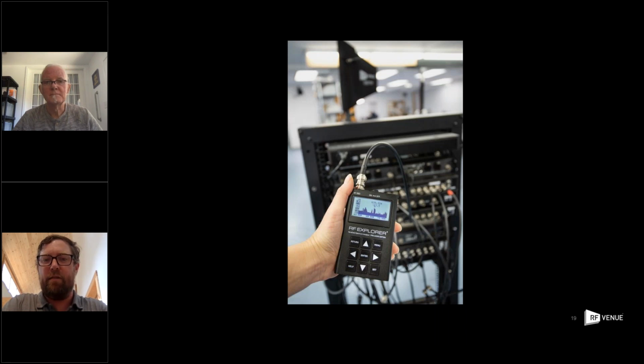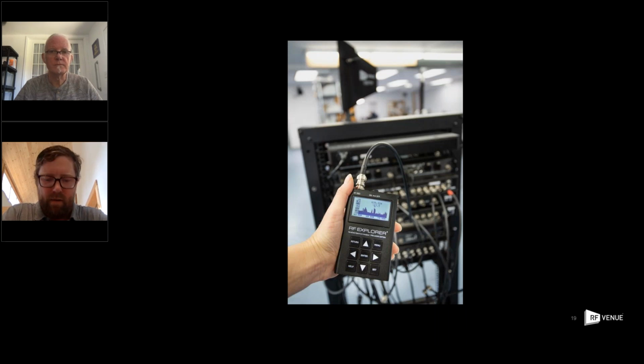If you've got a bunch of wireless mic signals that are, I don't know, minus 50, 60, minus 40, 30, pretty manageable. If you've got a bunch of signals that are plus 20, 30, very different situation, both on the analysis side and on the coordination side, because those relative differences are massive in terms of their impact on the overall spectrum.